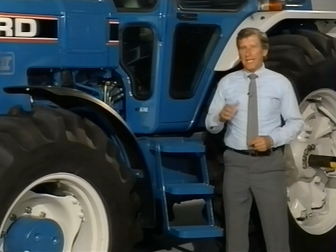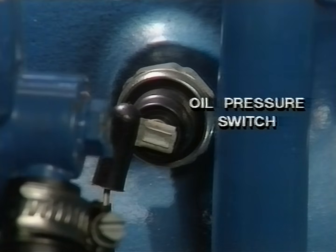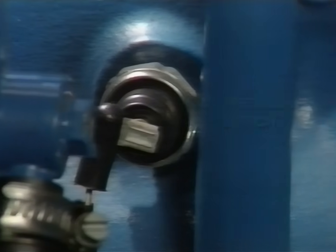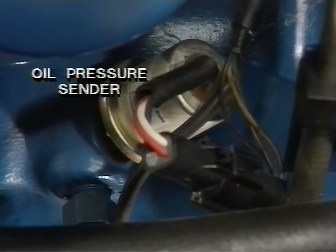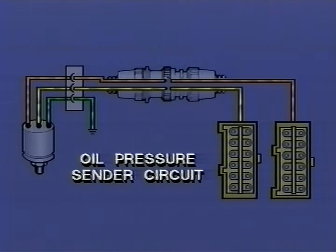On this side of the engine are the engine oil pressure switch and sender. The engine oil pressure switch is a simple on-off device that opens when oil pressure rises above 10 psi. But the oil pressure sender is more complicated. The EIP monitors a 5-volt signal it sends to the oil pressure sender. Variation in oil pressure causes the voltage to change, causing the EIP to change the readouts and warnings accordingly.